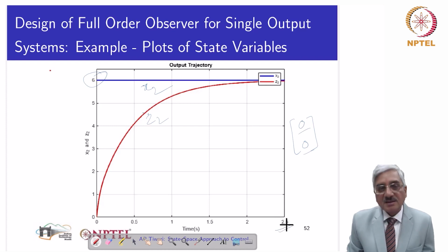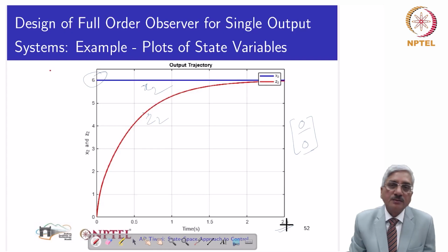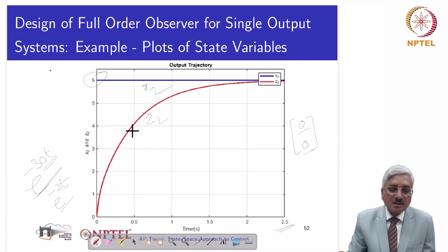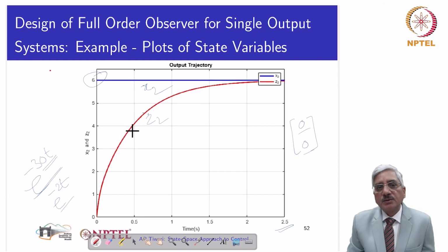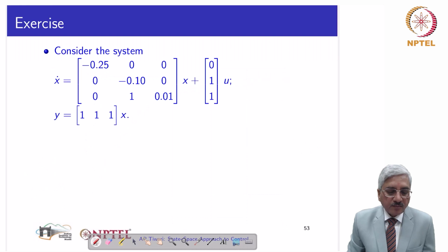It is not in that sense a large t, it is a small t, and it is dependent on the eigenvalues of the observer. So its response will be characterized by e power minus 30t and e power minus 2t. So essentially e power minus 30t will become 0 very fast. So this response is essentially characterized by e power minus 2t. That is it.